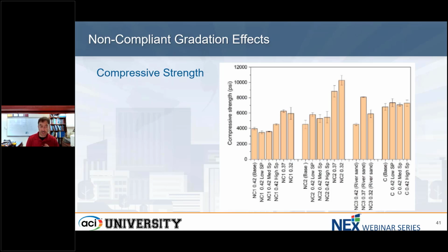So we need the plasticizers to maintain the same equivalent workability of our mix, but we can actually get even stronger concrete than the target by reducing that water cement ratio. Yes, of course, you reduce water cement ratio, you get stronger concrete. That's known. But the question that was unknown, and actually it's real, you can't even find literature on this, is can you do it with non-compliant aggregate? And the answer is yes. Not so great when it's too fine. Yes, when we have it coarser.